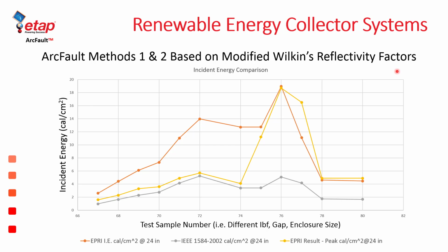So what you will expect to see when you use the ArcFault enclosed simulations is a more conservative set of results to account for some statistical events where the incident energy could be higher than what is predicted by the IEEE 1584-2002 model when applied to this particular equipment range.